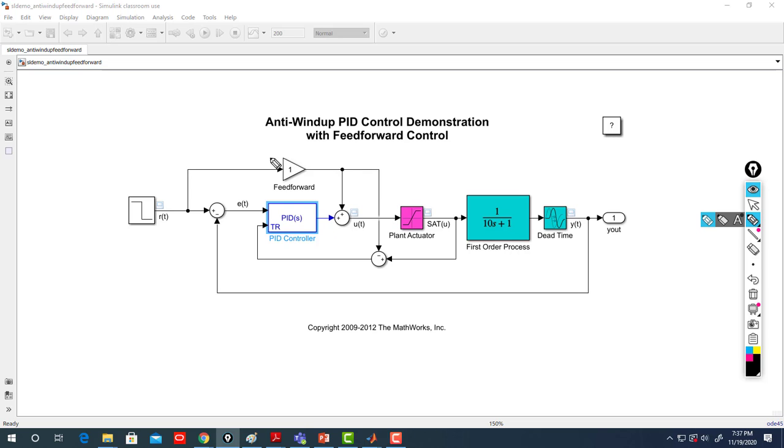Basically here we put a gain, and this gain, which is here, is not 1 in general, it is 1 over the DC gain of your plant. Because imagine that's the DC gain of my plant, assuming it's equal to A, or K if you wish.